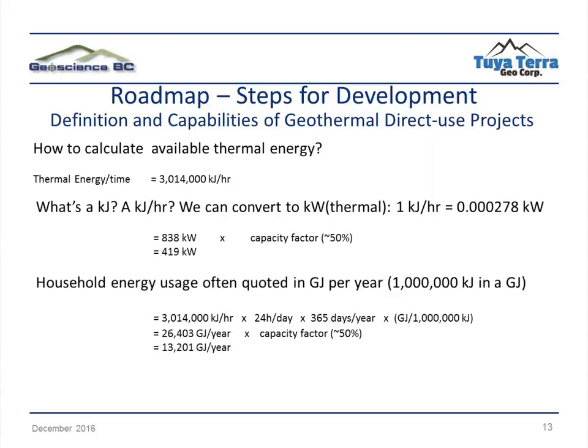So what that really means is that even though you've got this available thermal energy, due to various losses in equipment and distance to transport the fluid, you are losing a certain amount of heat. And in this case, we're assuming that that loss is 50%. So that takes your final thermal energy to approximately 400 kilowatts.